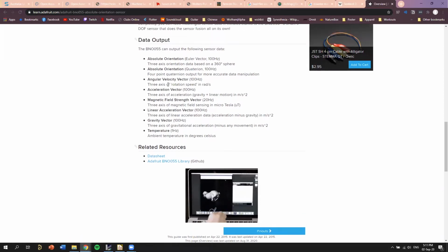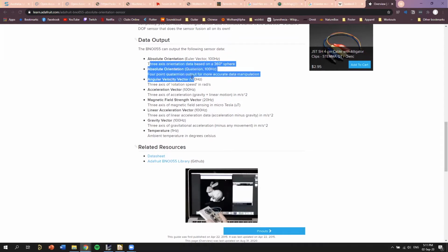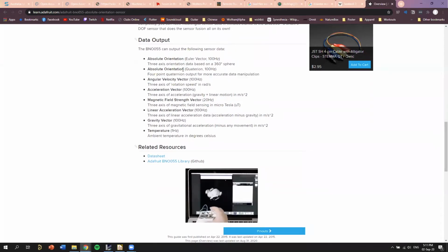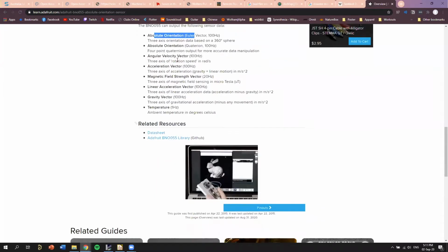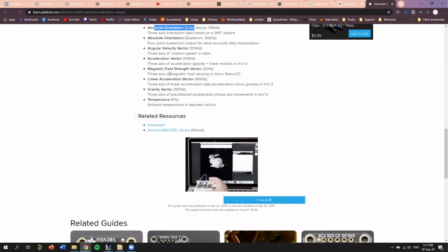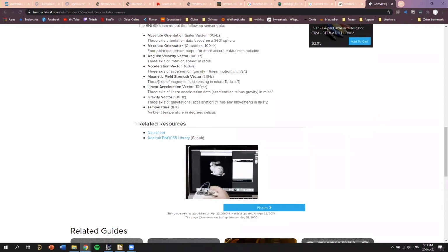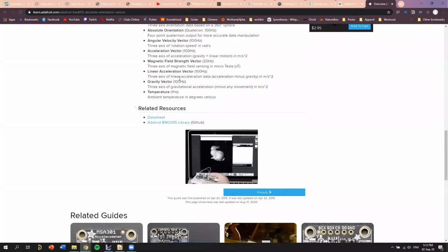Typically this is also from the angular velocity. You can read that, but it already does the integration because it passes out the absolute orientation. So you integrate that to get these. Great thing about the chip is you don't have to do that. It's also got a magnetometer on it. So rather than integrating your gyroscope, you can use the magnetic field of the Earth. It's basically a compass, and that can tell you what your orientation is.